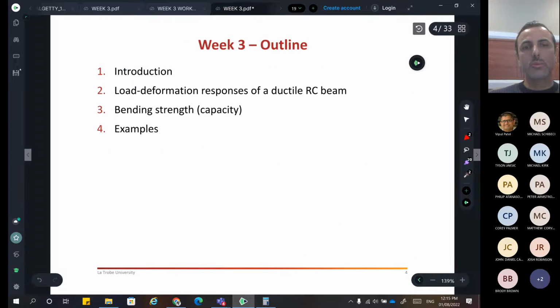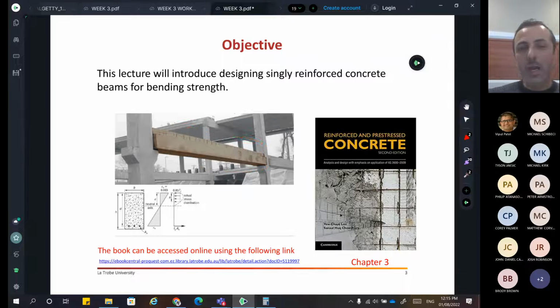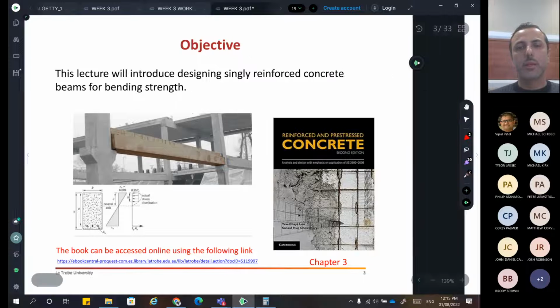Sometimes when we need to do precast, this is for reasons like it's very high and they don't want to prop it. They can't prop it on site. It's just going to cost a lot, and there's no point. That's where builders are going to think about precast sections. So they're going to build the beam in the factory. Usually I would say this is pre-stressed, but this is not our topic. So it is a reinforced concrete section, whether RC or PT, but they're going to build it in the factory, then just crane it and put it on site.